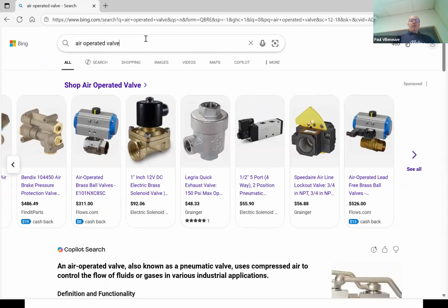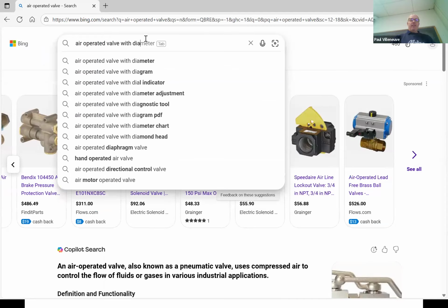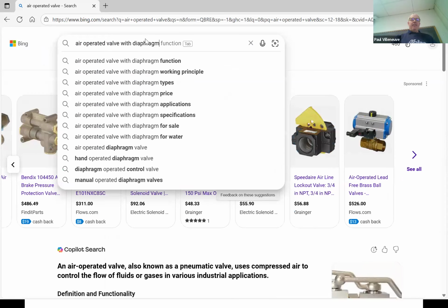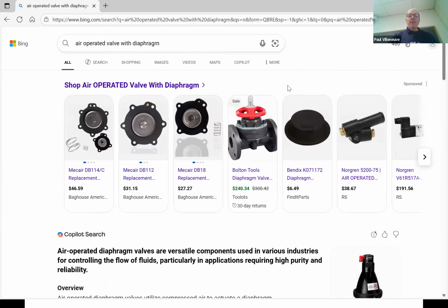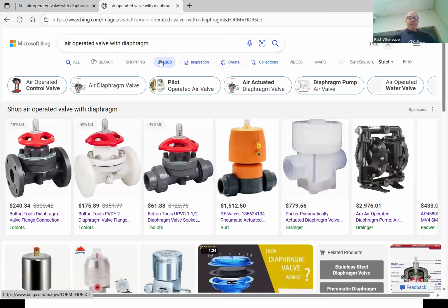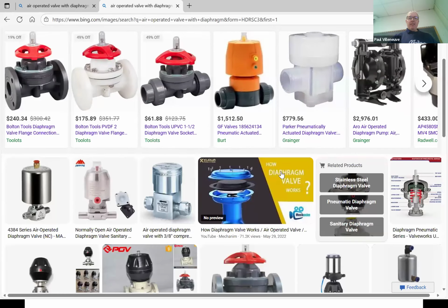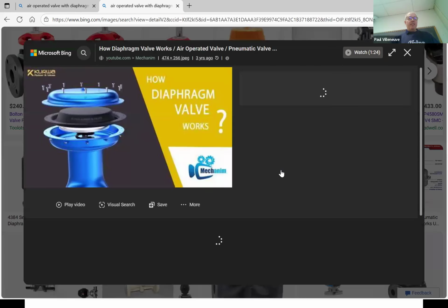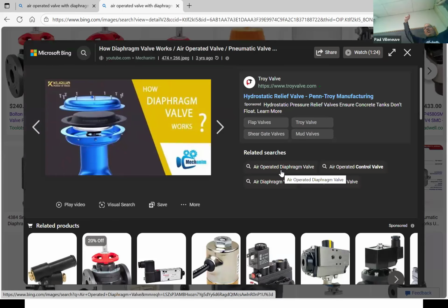But the ones that I used to have had a giant diaphragm on the top. Let's see. I can't remember the name of the companies that made them. Like here. This is the one that they used to have. So they had this giant diaphragm on the top, and the little electrical control signal would put air above or below to either push or pull on the valve.